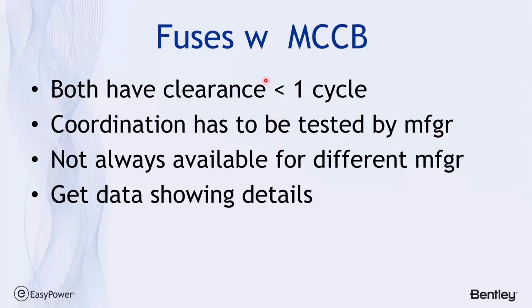Now, this is where things get a little bit more complicated. Fuses coordinated with molded case circuit breakers. They both have clearing times, usually better than 1 cycle, guaranteed by the design. So the coordination has to be tested by the manufacturer. It's not always available for different manufacturers.